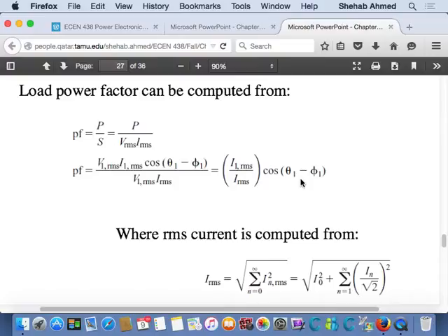If you have a poor power factor, what happens to your average power? Average power is IRMS times cosine of the angle between the voltage and current. So it's IRMS times the power factor. If your power factor is 1, then the utility is charging you for the full amount that you're consuming. If your power factor is 0.5, they're only charging half.